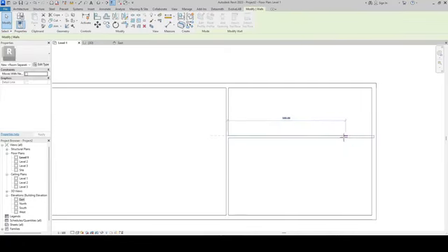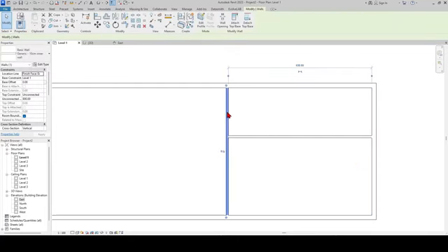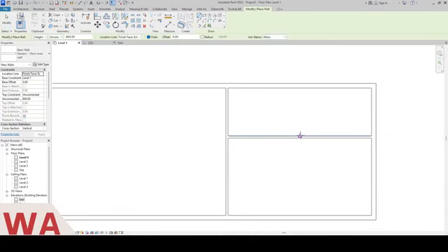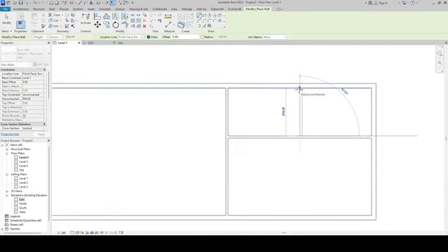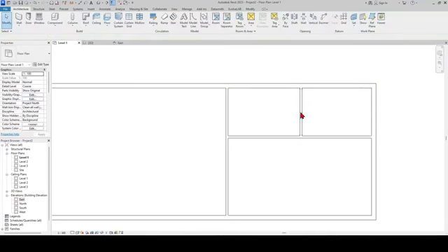You can adjust the length of the wall you draw by dragging it as you like. When you click on it, you will see its distance to other walls. Let's divide the room in half from the middle point of the wall, where the triangle sign appears. We also need to click on the measure command that we see in the upper part to measure the distance between 2 points.